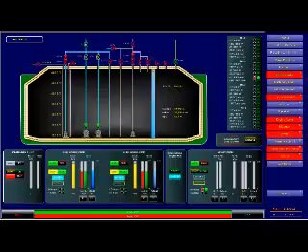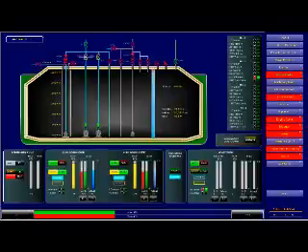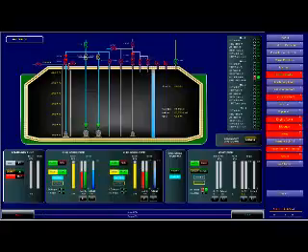Yeah, open it fully. So this is, I think, doing in auto, no? No. The pump is auto, not the discharge. Okay. Check the amperes, whether the load is okay or not. Now, this is not opening fully. Okay, that's fine. Leave it there, because you have put it on auto. Okay, that's fine. So can you now check the sounding in your number 2 tank?